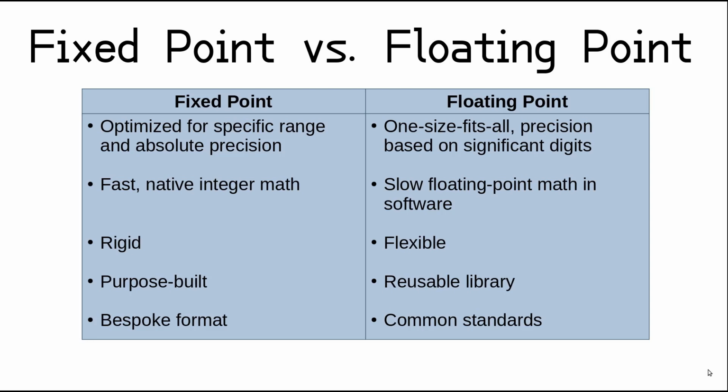Fixed point means that you are still doing integer math, but redefining your numbers to have a fixed number of bits at the bottom dedicated to a fraction. For instance, you could do a fixed point implementation with precision of 1/4 instead of 1. So the lower 2 bits of your value are the fraction, meaning 1 would have a value of 1/4, 2 would be 1/2, and 4 would be 1. This, of course, limits your upper range by the number of bits you are using for your fraction. So an 8-bit fixed point value would max out at a value of 64 with 1/4 precision.